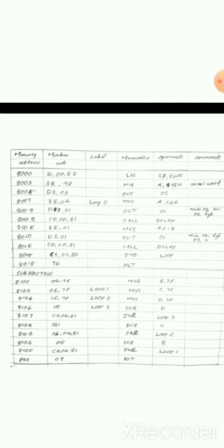The content of the DE pair is decremented in a loop. After each decrement, the contents of both D and E are logically ORed, and the result is 0 only if the contents of both D and E are 0. Otherwise, control goes to the beginning of loop 1. The repeated execution of loop 1 continues until the content of the DE pair becomes 0. Now the result of the OR operation is 0, and control goes out of loop 1.